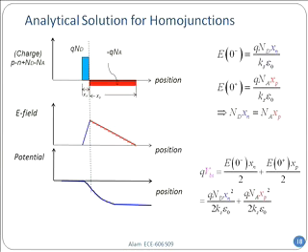So in this equation, how many unknowns do I have? I have unknowns of Xn and Xp. Nd and Na I know. Okay, so I need another equation. Step down one more time. QVBI, how much is QVBI? Well, QVBI is the area under the curve under the electric field.